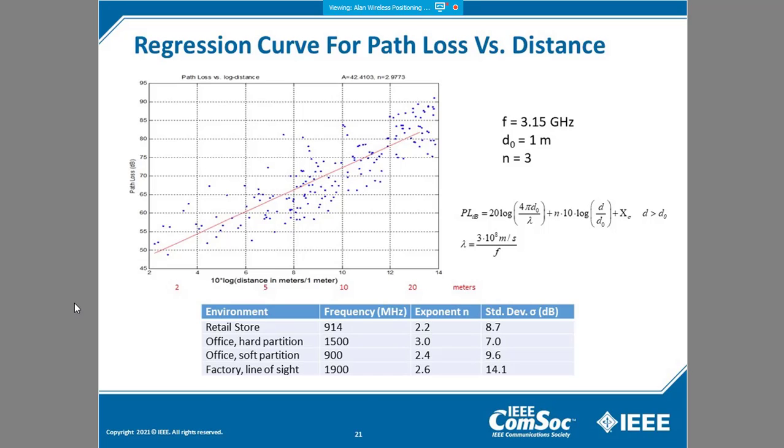So if it were, say, 30 nanoseconds, then it would be an accuracy of around 10 meters. And again, this difference between the transmitter and the receiver would get greater as time goes by because the clocks are not synchronized. There is drift between them.